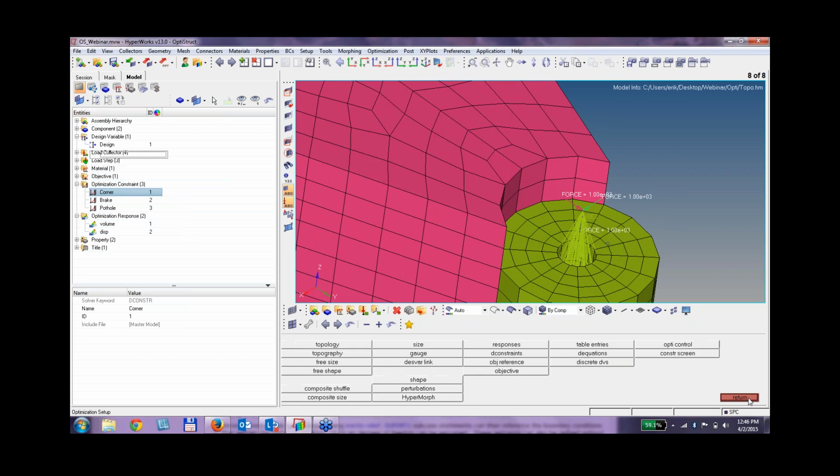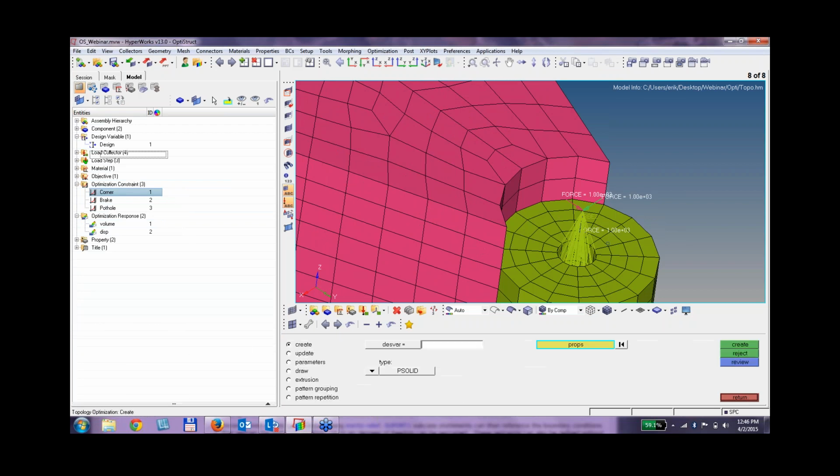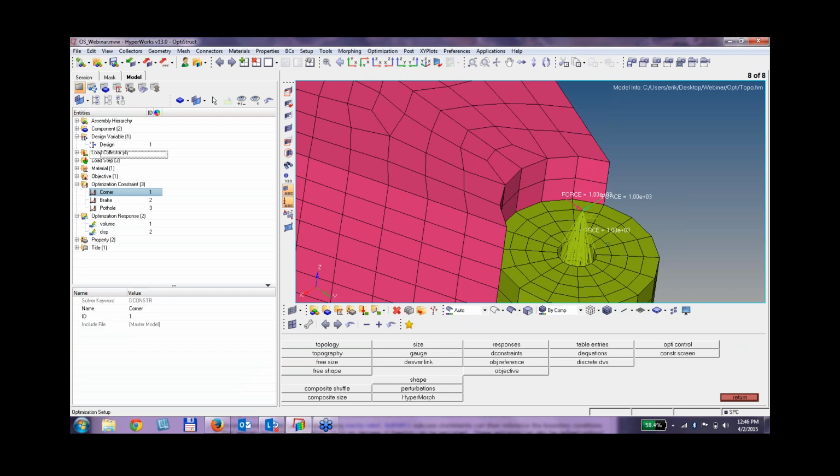I believe also there's a stress constraint on here. So if you come here, nope, I guess they didn't include that on this. But you can include stress constraints. So you can say, these are the limits I want to go. And as we mentioned earlier in the modal analysis, I can say, I don't want my frequency to be above or below a certain value.